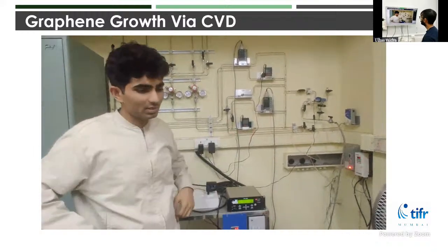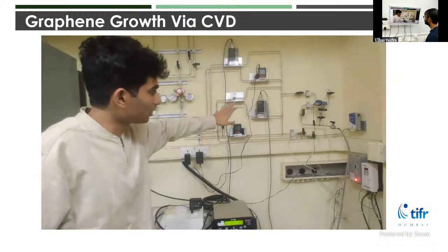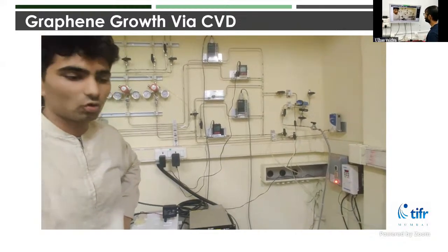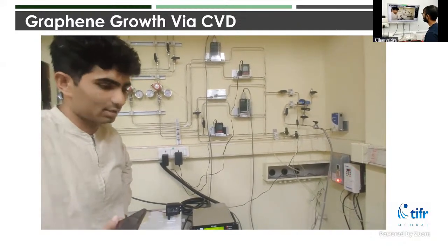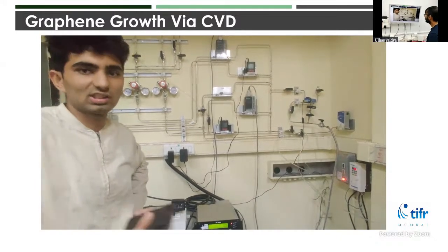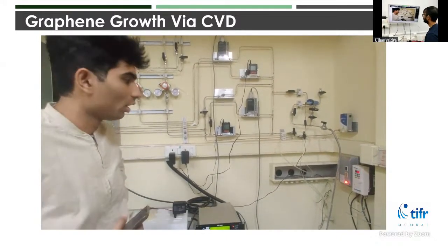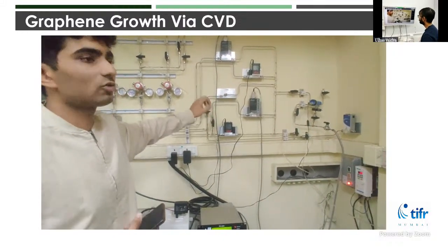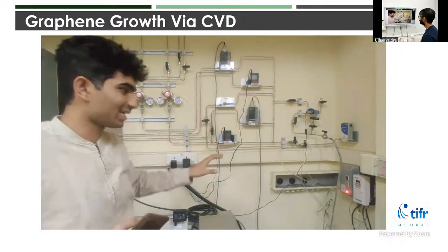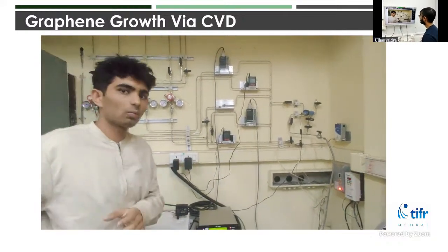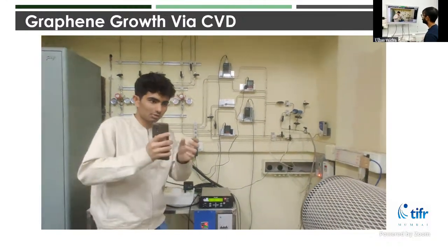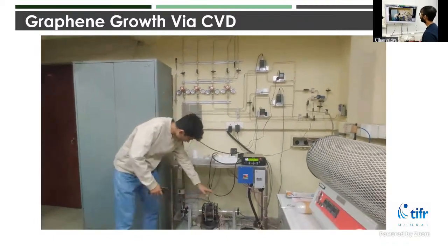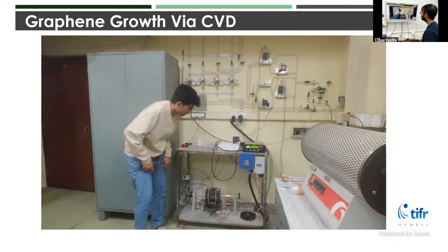This area that we have over here also helps us establish a good amount of control over how much gas is going inside the CVD chamber, or the CVD tube that we have, which we'll show you subsequently. These are mass flow controllers, and mass flow controllers give you precise control over how much gas is being sent into your system. Now, if you have a look at our CVD system, this is what it looks like, particularly the furnace part.